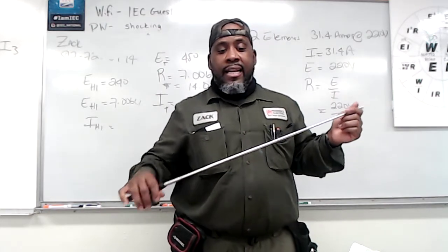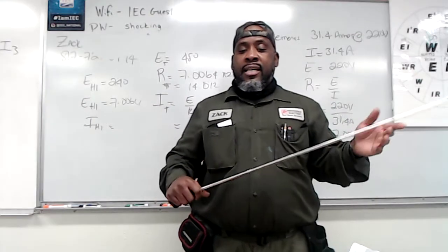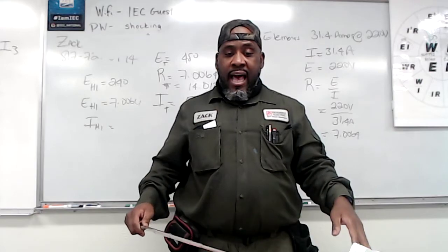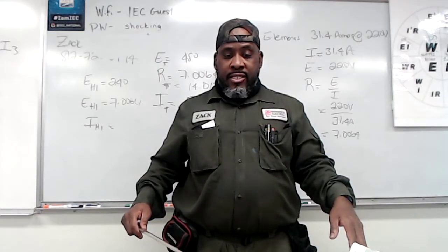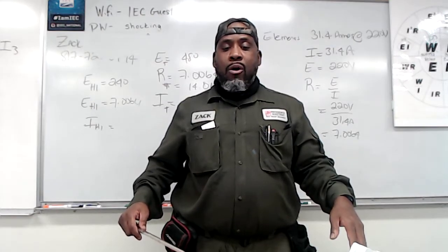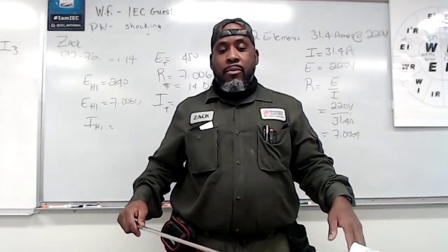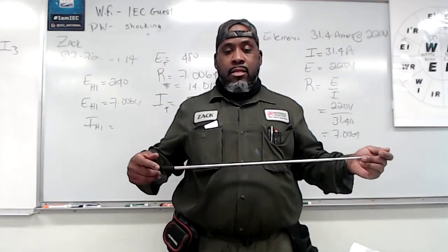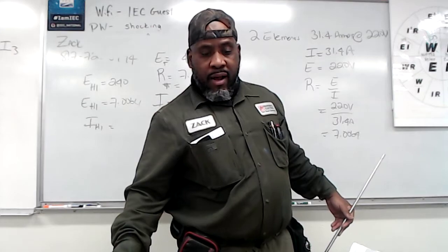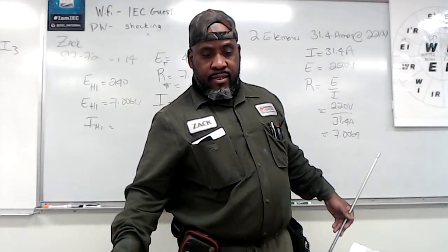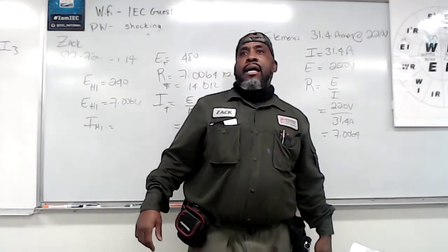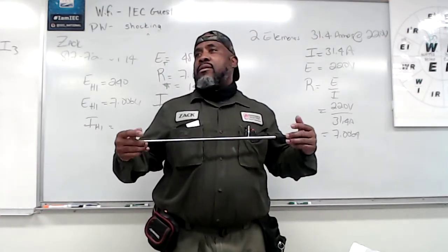Let's look at the second one. The right half of the receptacle is connected to circuit 22 and constantly hot. So number 1 won't meet that. Number 2 won't meet that. So that means it's probably neither one of those, right? Neither 1 nor 2 should be it. Any questions on that one?